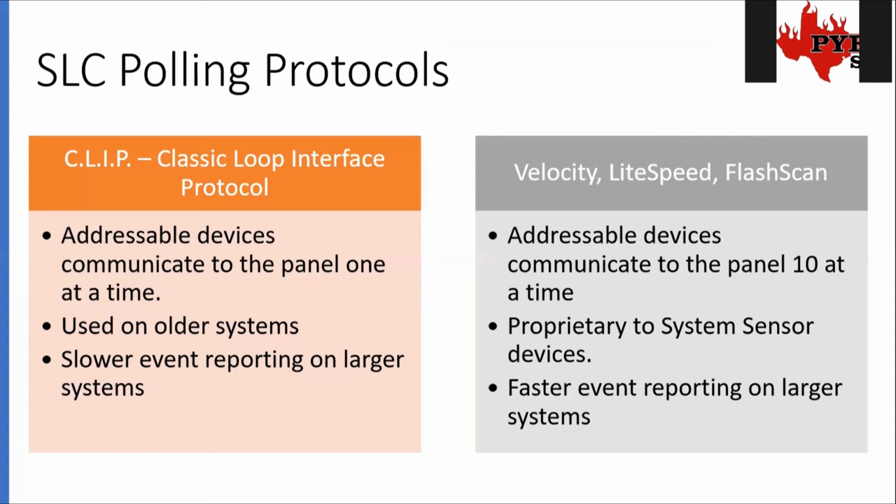And when they were first coming out with it, my first thought was, well, we just need to put all Ivory devices everywhere, because then that's what we'll have in stock, that's what we'll have available. But there's a pretty significant price difference between them. And so we realized it was beneficial in our favor to go ahead and put the white devices in all the new systems, and then we'll just have some Ivory devices we keep on hand for service applications. So if you are going on a service call, if you are working in an older building, make sure you know what type of panel you have and what kind of devices it communicates to.